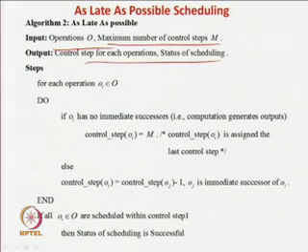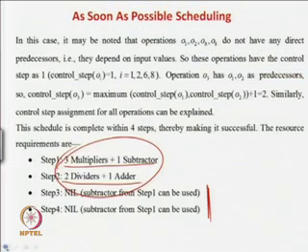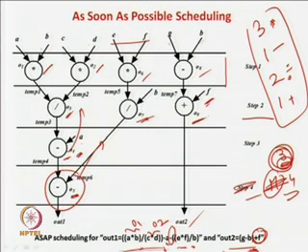So, again like the earlier case, we are going as late as possible. We have to find all the operations Oi which do not have any immediate successor. If you look at this, O9 is actually an output, and O5 is an actual output. They do not have any kind of successor, nobody depends on them. So we can schedule them as late as possible.